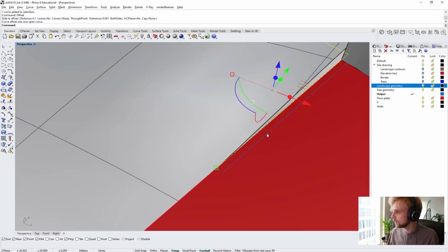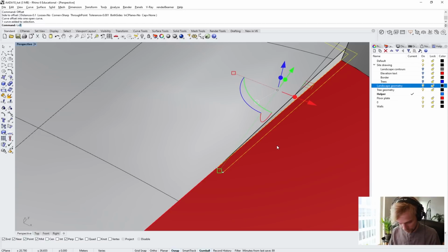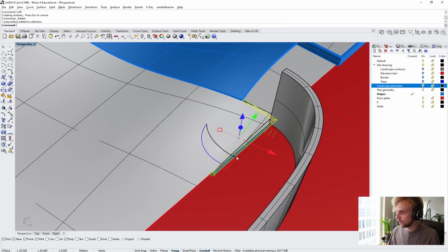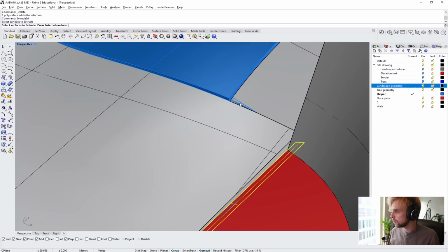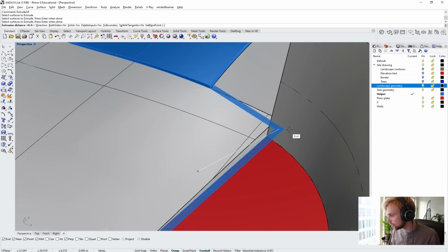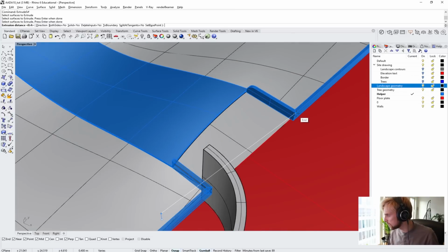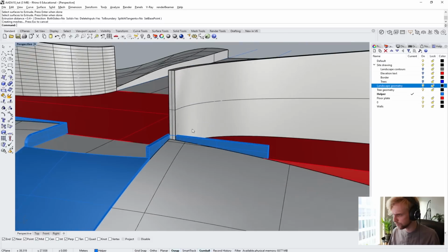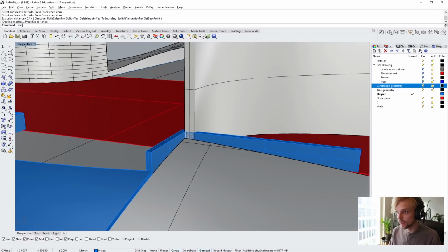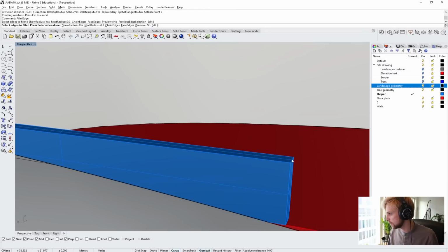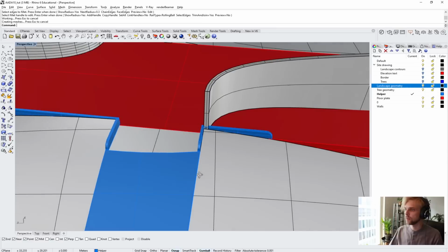Offset, like that. Loft, delete. Extrude surface, select this and this up by, do we use the same, maybe we should use the same height, like that. So I'm just snapping to the top of this. Fillet edge, 0.3 is great. Perfect, okay, we're done.